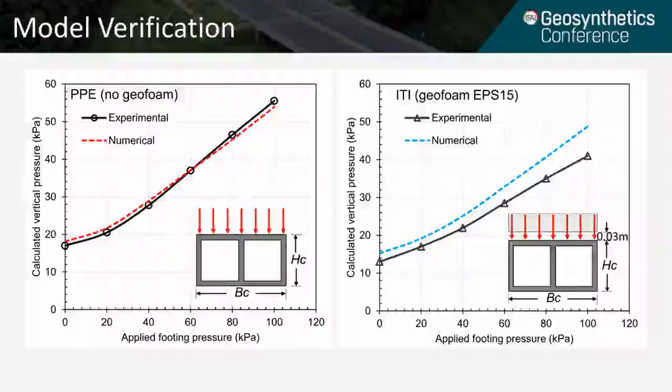It's good to mention here that even though we're showing the pressure agreement for the model verification, we did not rely on this condition only. We also tried to verify the model with the behavior of the footing settlement, geofoam compression, and also the overall behavior between the two experiments, the experimental and the numerical part.